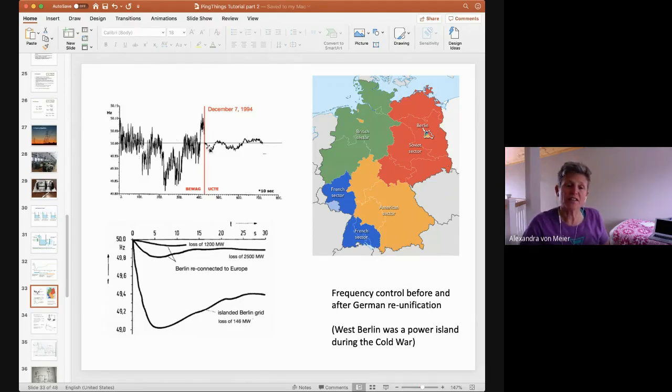electricity. And you could see that by virtue of being in a much larger system, which then is also connected to Europe, the volatility of the frequency became much less. And also that when Berlin would lose suddenly a generator, the frequency wouldn't drop down so far. So this is in the larger system, whereas in the islanded system, the loss of one small power plant would bring the frequency way down to 49 hertz. But we didn't notice this as consumers. We didn't notice this because all the relay settings were set to permit that, and the lights stayed on very nicely.